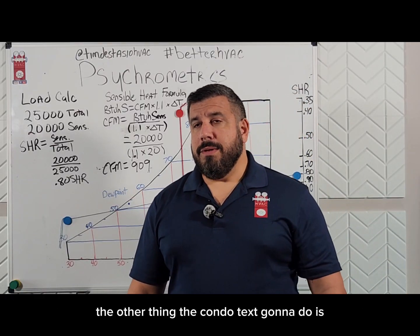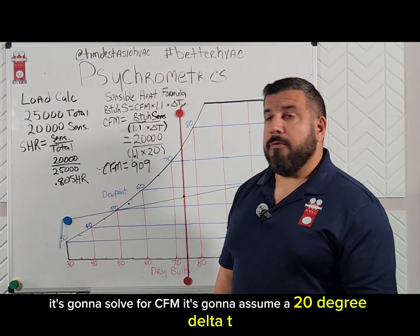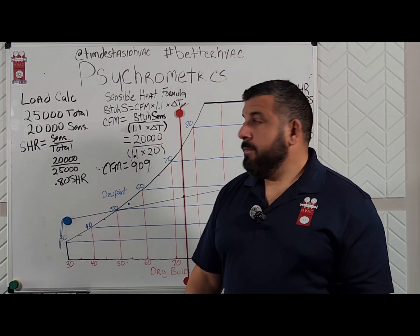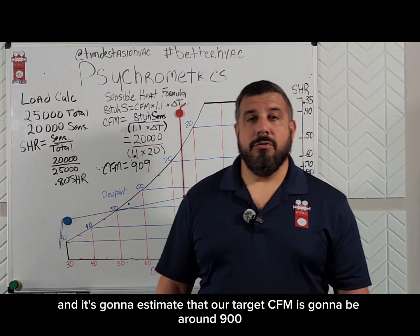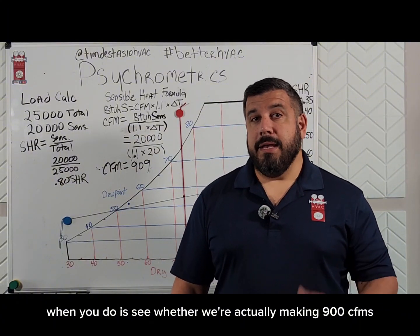The other thing that Conduit Tech's going to do is the sensible heat formula. It's going to flip it around. It's going to solve for CFM. It's going to assume a 20-degree delta T, and it's going to estimate that our target CFM is going to be around 900 CFMs. Now, the next thing we need to do is see whether we're actually making 900 CFMs.